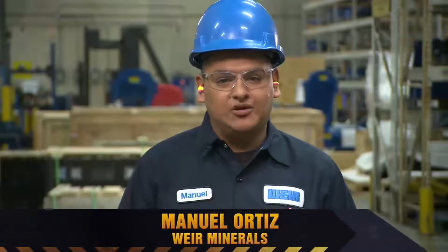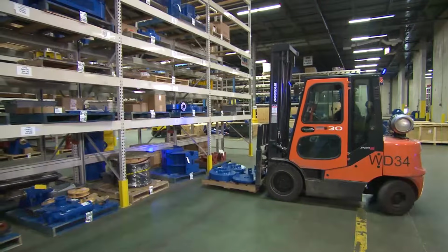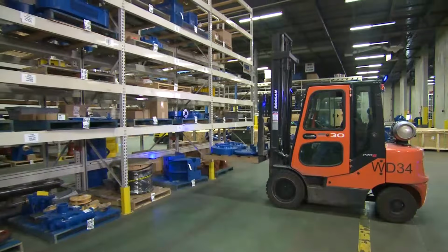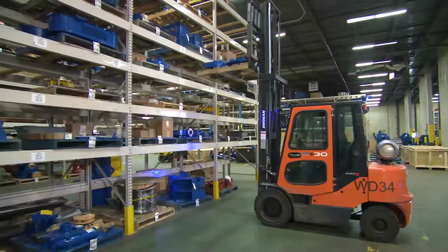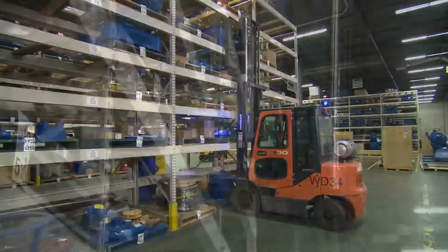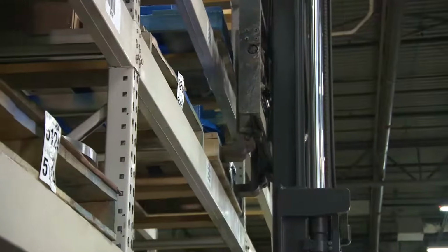I'm gonna show you how to break down the steps for placing a load. First, stop the forklift in front of where you want to place the load. Then, slowly raise the load to the required height. Move forward slowly with the raised load. Position the load for placement and tilt it forward so it is level. Next, place the load squarely and straight.